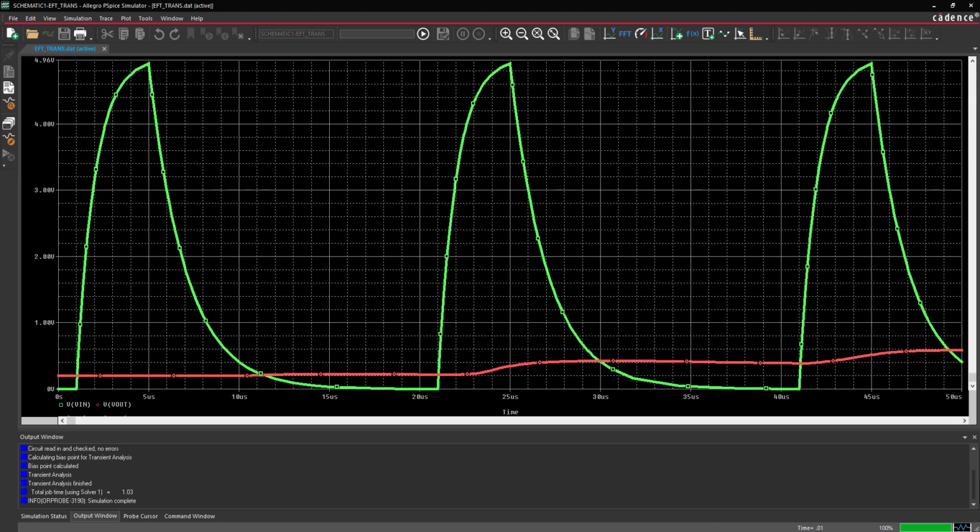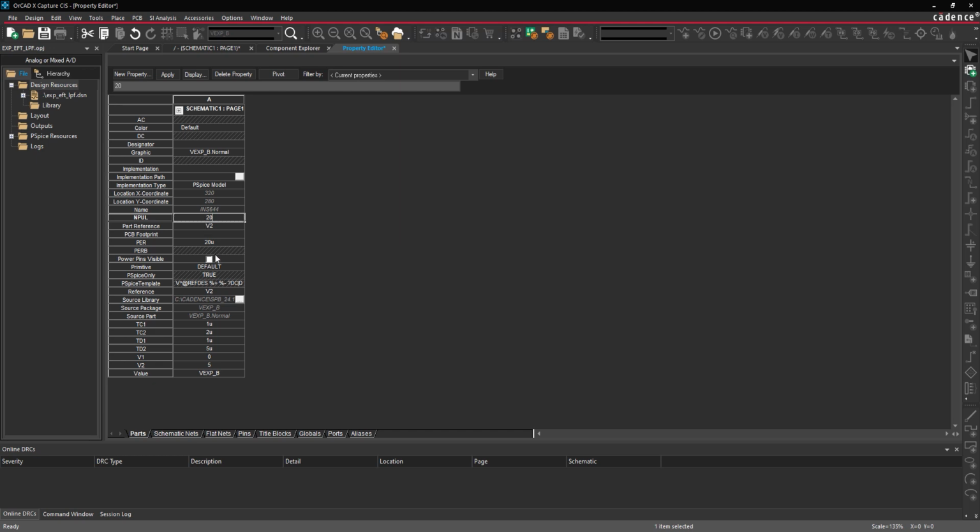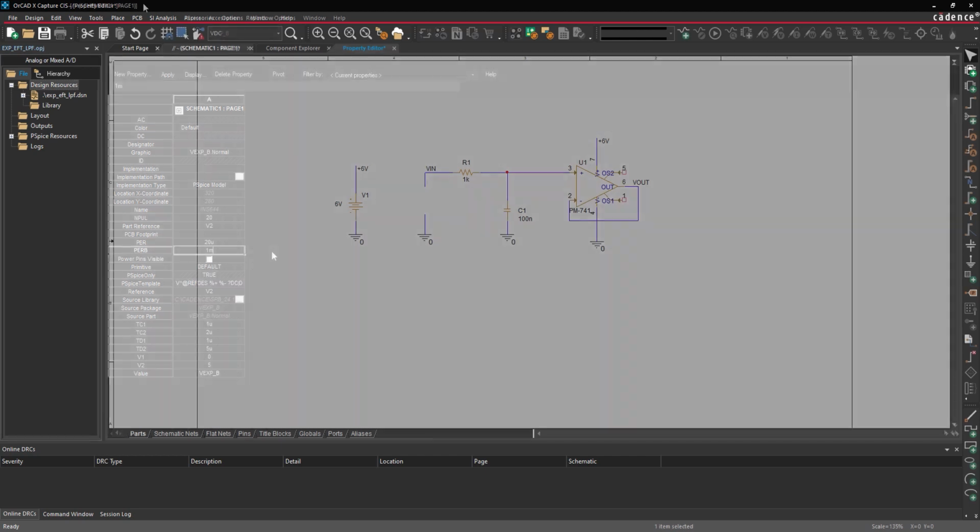EFTs are simulated as a series of pulses created at a certain interval, then held, then repeated after a longer period. For this example, we will create an exponential source that creates 20 pulses 20 microseconds apart every millisecond.